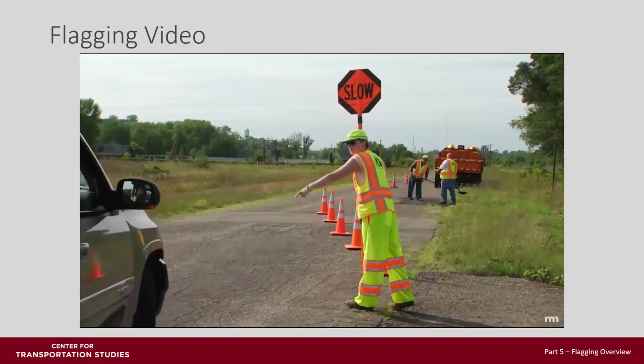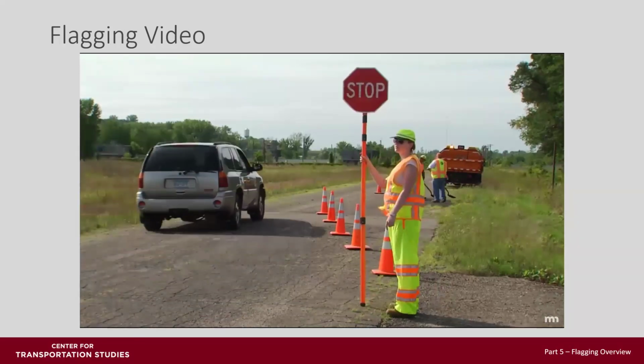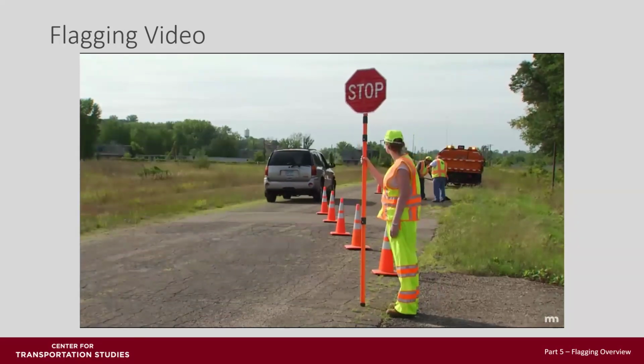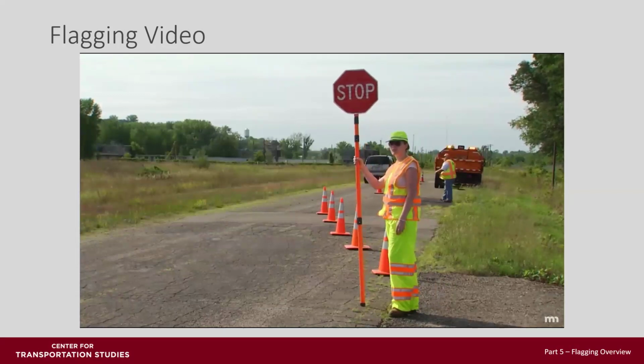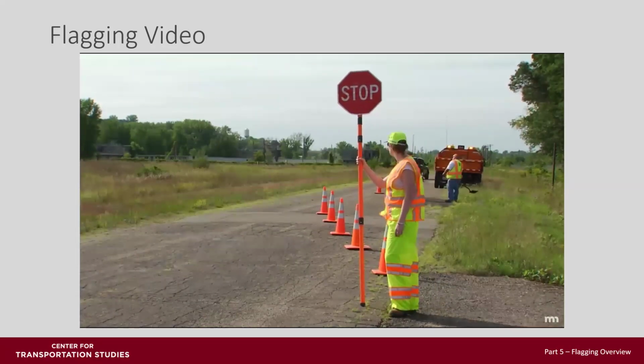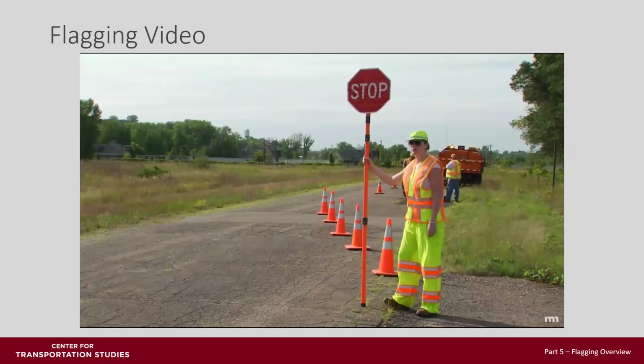The flagger stops the traffic approaching in the closed lane. When the open lane is clear, the flagger allows traffic to proceed. Remember, a single flagger operation is only acceptable for low-volume conditions where there is good sight distance from both approaches and the work area is short.